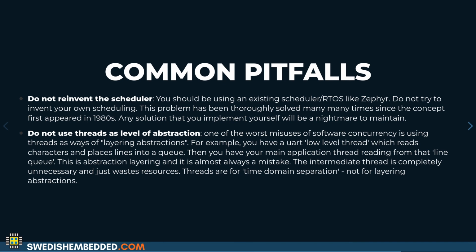You don't want to create threads unnecessarily. So try to read as much as possible in the main thread, in the caller thread, really. You should be utilizing semaphores, you should be utilizing work queue items to structure the sequences of your application, to structure any kind of timeouts or delays, so that you can avoid precisely this pitfall of creating too many threads. So you want to avoid proliferation of threads. Don't create too many threads unless absolutely necessary.